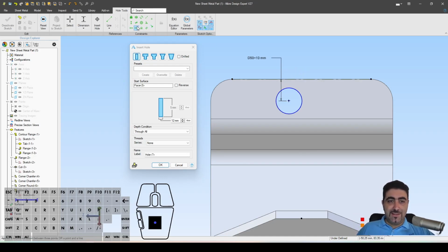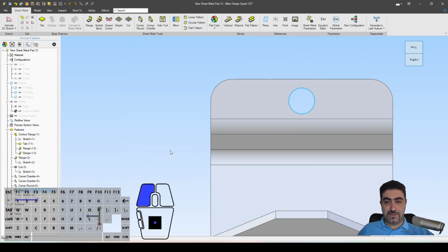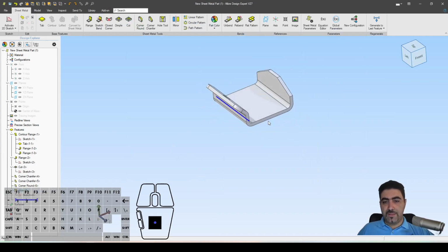And yes, that is done by using the midpoint constraint with 3 points. So 1, 2, I've now defined the line segment, and 3, I now place this point on the perpendicular bisector. I also have a dimension here to locate it along that perpendicular bisector. So this is now fully constrained. I can hit OK, and I'm good to go.